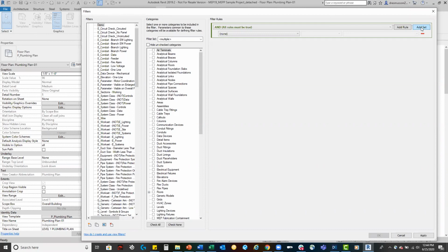it's just for data that you can pop on the end of a fitting or pop on the end of the pipe, but you can use that to redesignate what the system is, what the flows are, and everything there, so that the pipe from that connect into existing point then carries information down it for the rest of the system. So those are some workarounds that I've used in the past to be able to get over a lot of that.